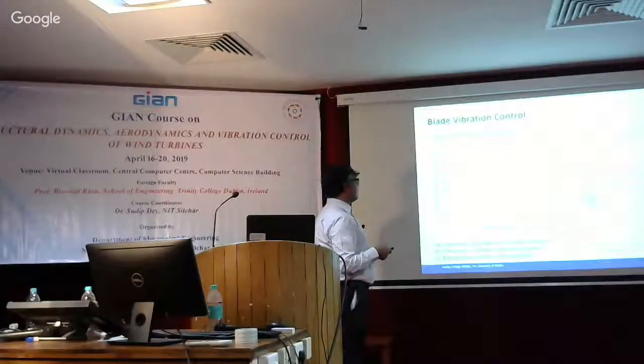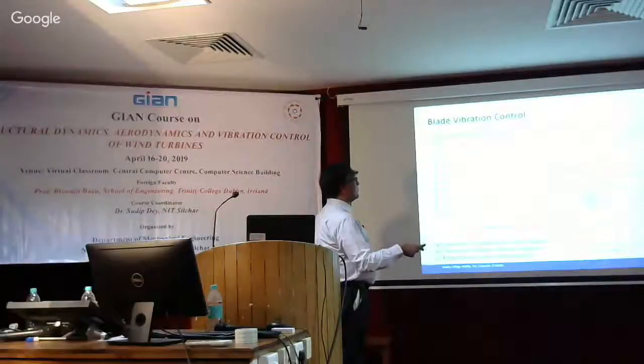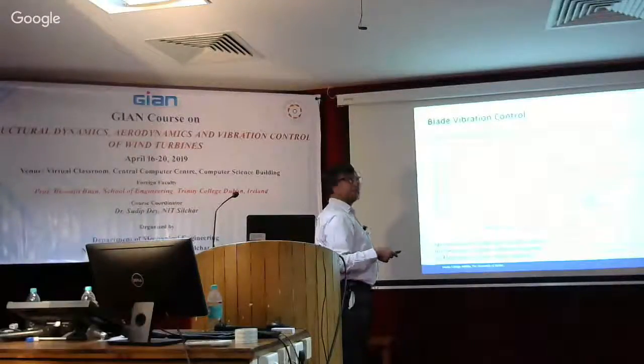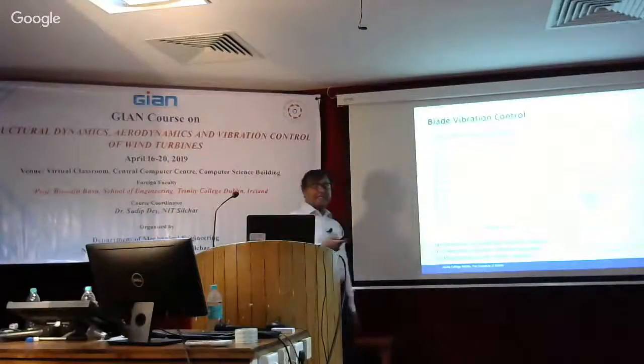But also here you can see that with a pitch angle of 4 degrees, we have a reduction of 40%. And if we increase the pitch angle to 10, then we have a reduction of 80%. But the price we pay is that here we have a power loss of 20%, and here we have a power loss close to 75%. Okay. So now we have a choice basically.